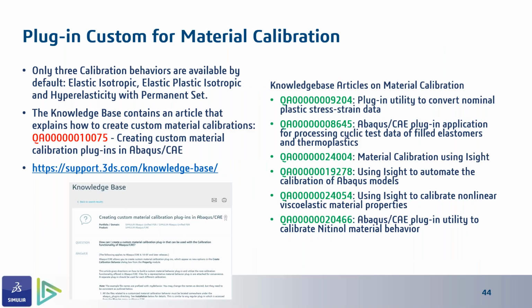For those who want direct calibration of other materials rather than just the elastic-plastic or hyperelastic, there is a support page called the knowledge base where you can get a plugin to do calibration of many materials, not only the elastic or the inelastic. There are viscoelastic calibrations and other material behaviors like nitinol you can even calibrate.